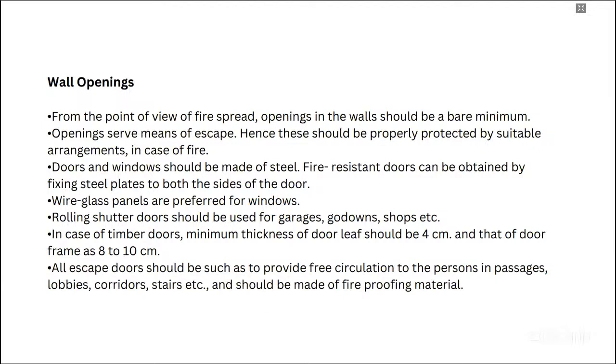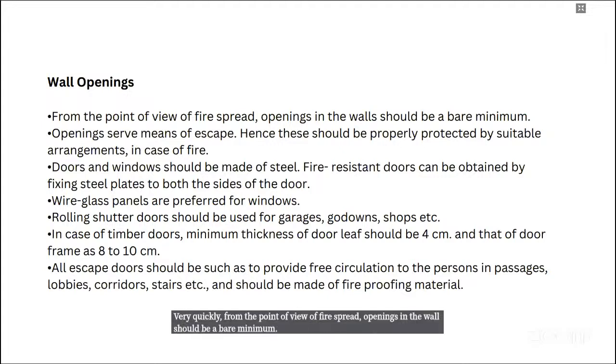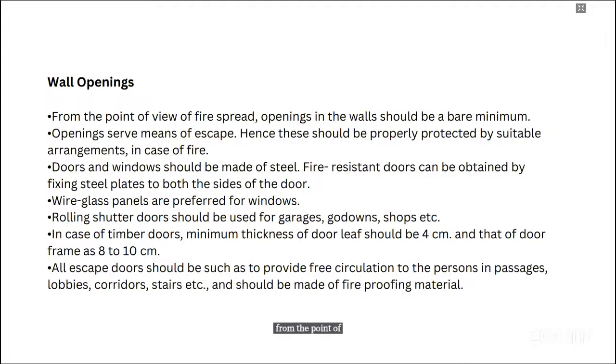Wall openings are being discussed, but let's go through this very quickly. From the point of view of fire spread, openings in the wall should be a bare minimum. Openings serve as a means of escape, hence these should be properly protected by a suitable arrangement in case of fire.